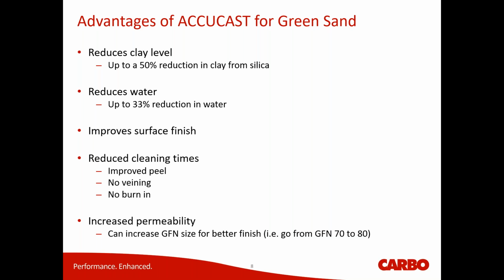Talking about permeability, again, it's kind of the driving force behind choosing what size aggregate you go with. The reasoning is a little different than no bake, though. In this case, if you're starting with a material that's close to like our ID70 for size and all the other attributes, you're going to want to go with an 80 most likely, and the reasoning is because with the 80, the permeability is closer. You might ask why, because you would think maybe higher permeability is better if all the other material attributes line up with the 70.